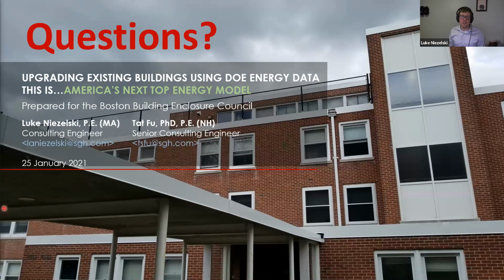Right. So for comfort level related to windows, triple pane is where it may be a factor. Generally speaking, triple pane doesn't pay for itself if you look at the payback period, because you get a little bit better U value, but it's a lot more expensive. One of the figures we're seeing is 1.4 million versus 1.8.